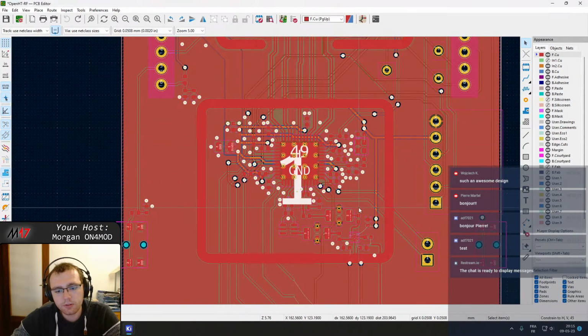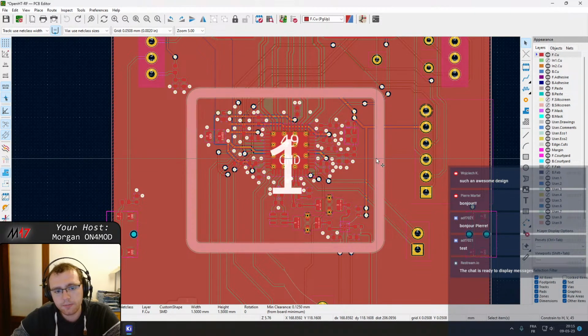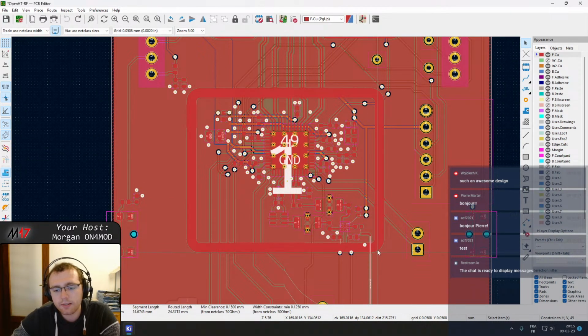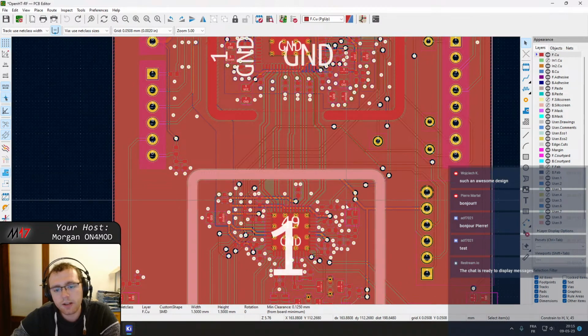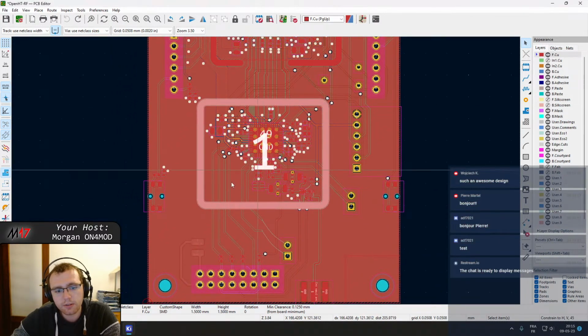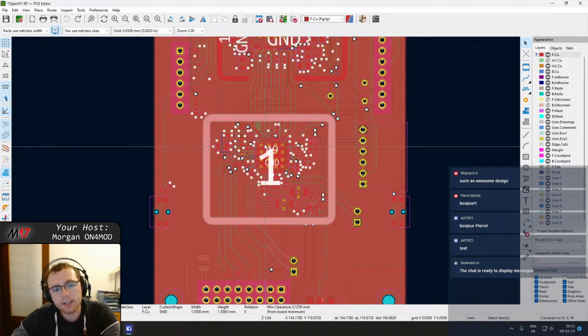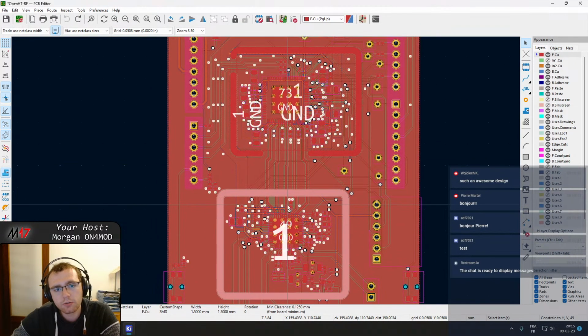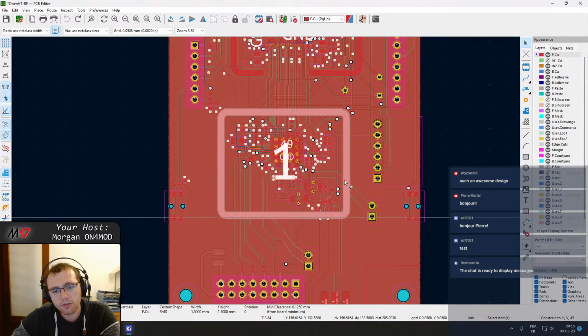But maybe you have seen too that this shield is not finished yet. We have traces crossing the shields, which is not feasible, even for the LVDS pairs. So what we are going to have to do today is finish routing some signals, and then create the required openings in the shield to take the tracks out of this area. And yeah, that's the plan for today.